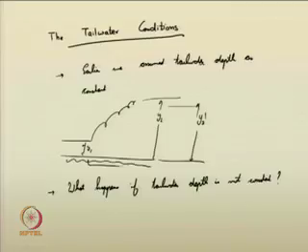So, if the tailwater depth changes, you know that the location of the hydraulic jump gets shifted. Now, again the stilling basin wherever you have designed may not become appropriate. So, therefore, you require a certain analysis where the fluctuations of tailwater depth are also taken into account, right.